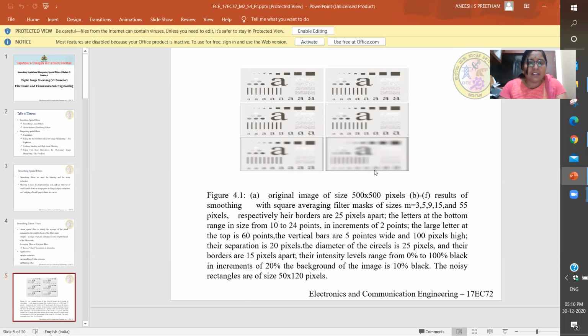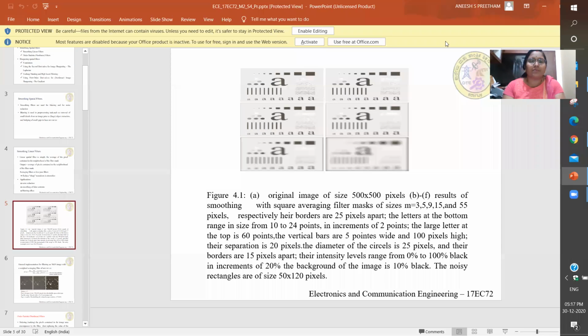This is a result of padding the border of the original image with zeros and then trimming off the padded areas after filtering. Some of the black was filtered into all filtered images but becomes truly objectionable for the images smoothed with the larger filters.